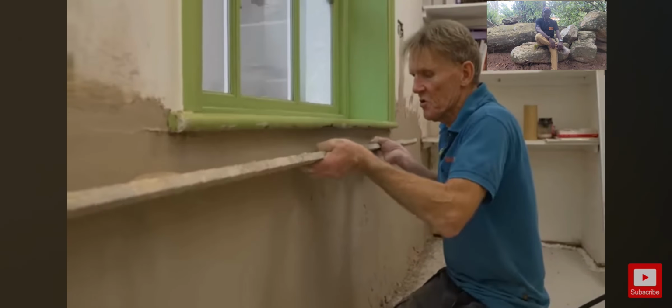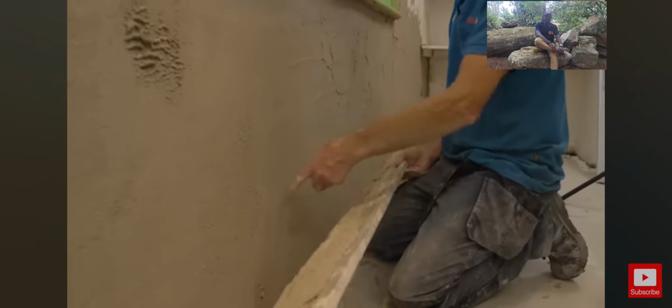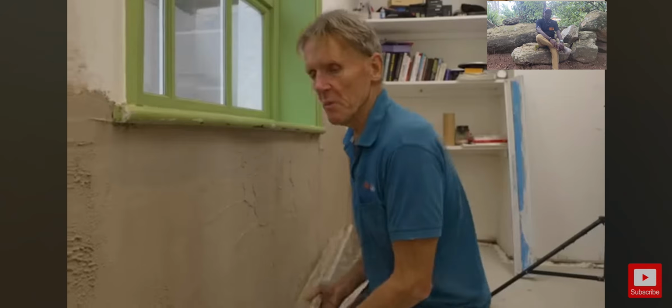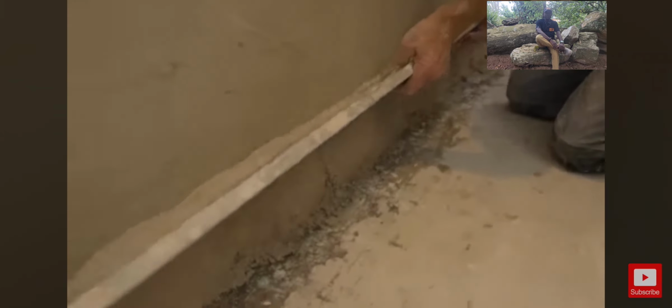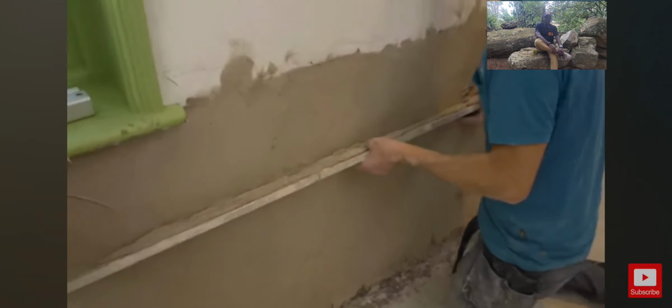And what I used to do is I didn't put it on thick enough, and then as I was ruling it off, it revealed loads and loads of low spots, and I had to go back over it and fill in the low spots. But if you do it this way, you've got plenty on there. Just rule it off. Still a little bit wet for doing that, but you can see you just carry on along the wall, and it just makes it a lot easier.